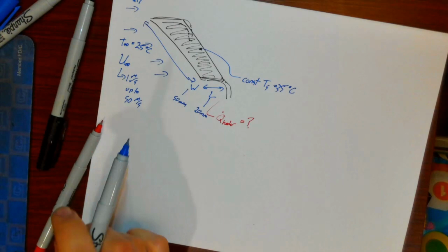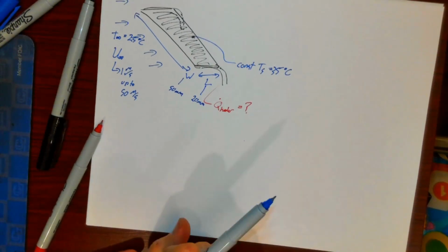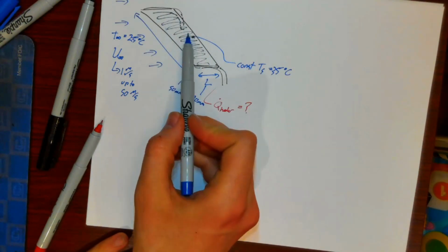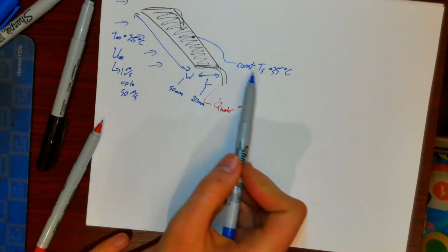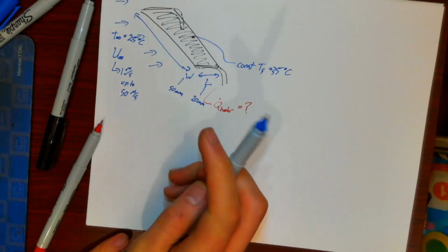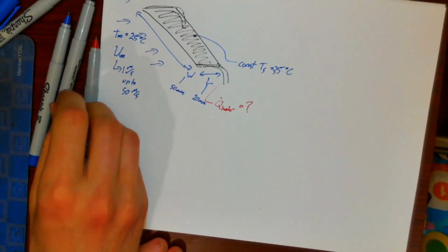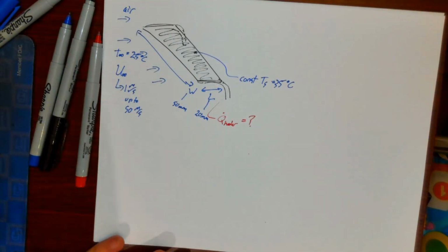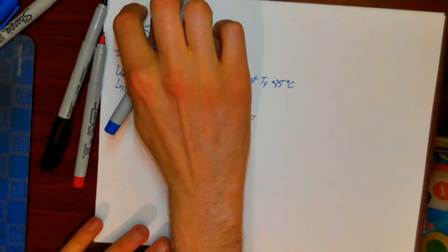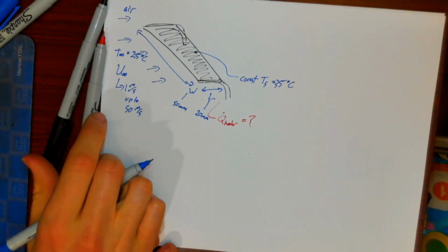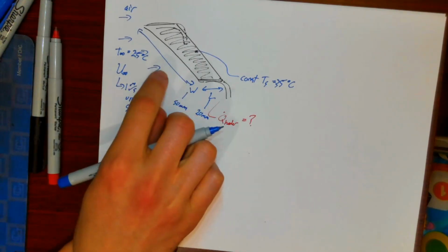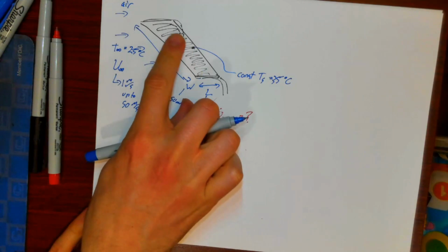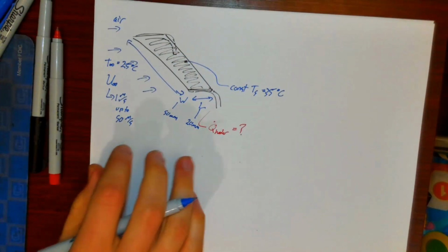All right, so let's say we had this device. This might be the kind of problem that you're given. Basically, how much electrical energy do I need to keep this double-sided strip at this temperature given these flow characteristics, and given that it's air flowing over it? Well, you can say, I anticipate there's going to be convection, and this is convection over a flat plate, so I'm going to need some properties of air in order to do this calculation.